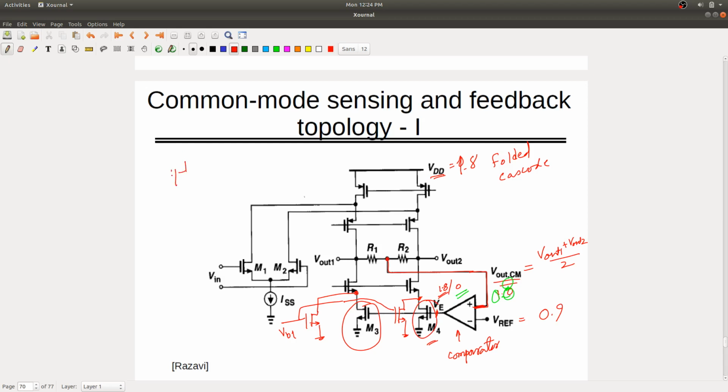So it's something like, earlier VB1 was already available, so there is a switch through which it's asking for current, or it will have more current flowing through this one. So indirectly they are increasing the current flowing through this branch, right? You can have multiple transistors, not only one, and the current flowing through is I, 2I, 4I, then this is called DAC based tuning.